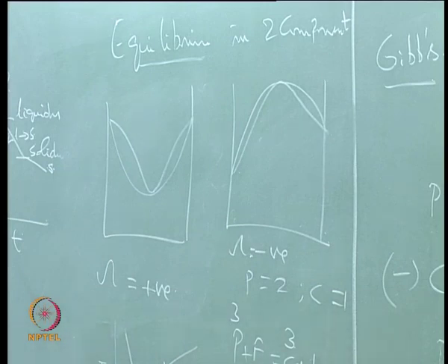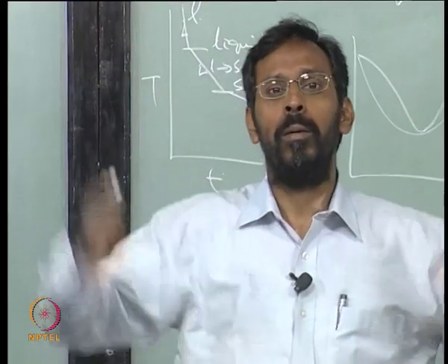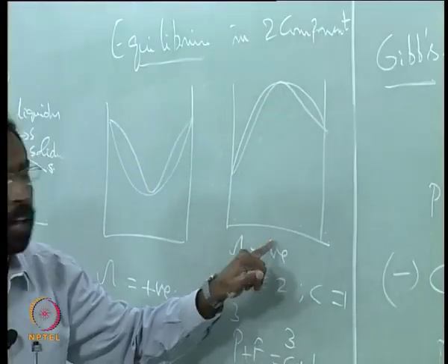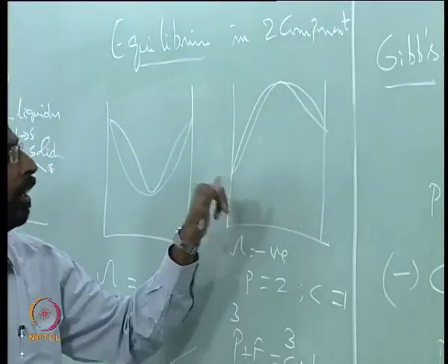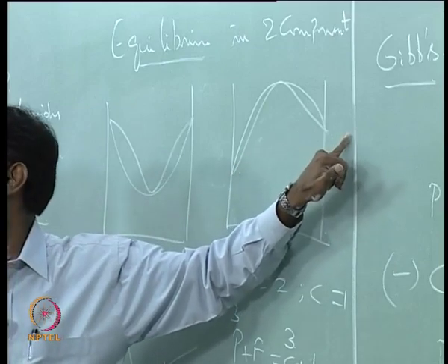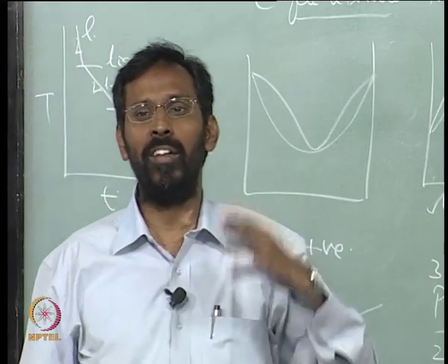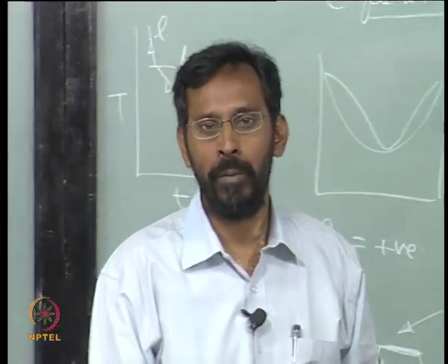That means there is an attraction between A and B. The A and B bonds are stronger and they do not want to break at low temperatures. So they retain their bonds even at higher temperatures. As a result, the melting point of the alloy is higher than the two individual pure metals. And in all such diagrams there is a tendency for formation of intermetallic compounds.